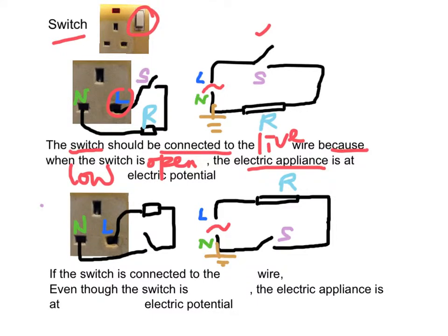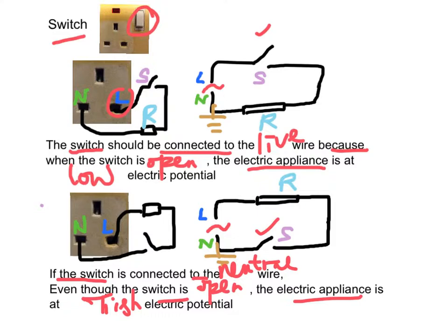However, if the switch is connected to the neutral wire, even though the switch is open, the electric appliance is at high electric potential, which is very dangerous.